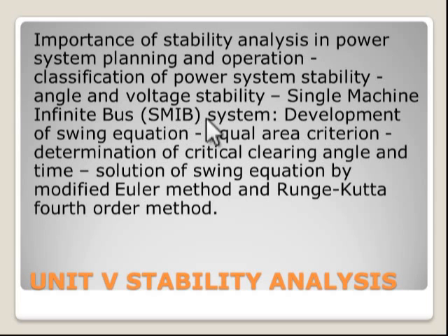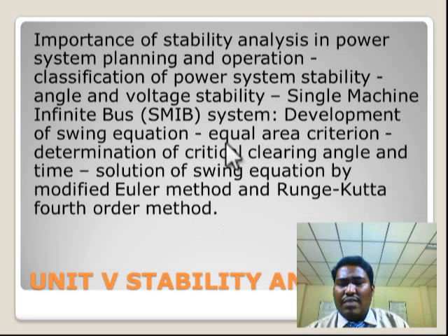We create our swing equation with the help of the rotor angle. With the help of rotor oscillations we develop the swing equation, and we characterize the equal areas for each and every power system. Stability should be maintained as areas. When we find the areas of the power system, we have to determine the maximum critical clearing angle and the maximum critical clearing time offered in the power system. These are the conventional ways to check our stability.